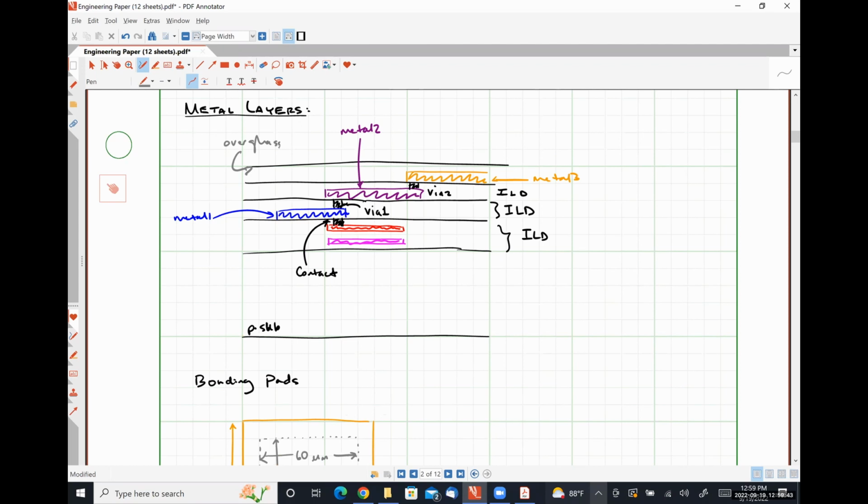If you had the metal layer fully exposed, you could get mechanical deformation of your bond pads and things like that. They could literally float off and detach. So this physically holds it down to the surface to maintain contact with the underlying layers and all that kind of good stuff. That's what the overglass or passivation layer does.